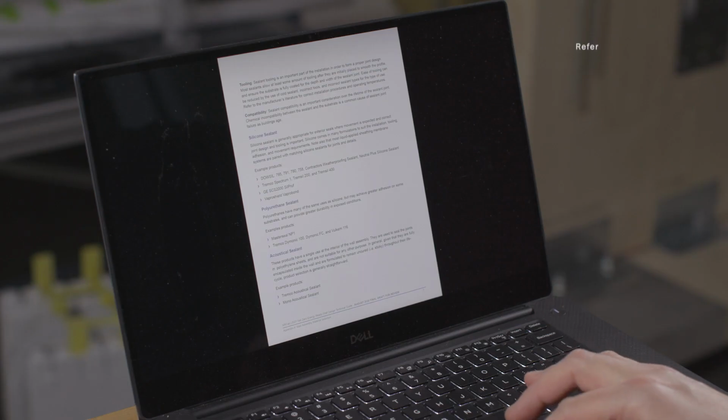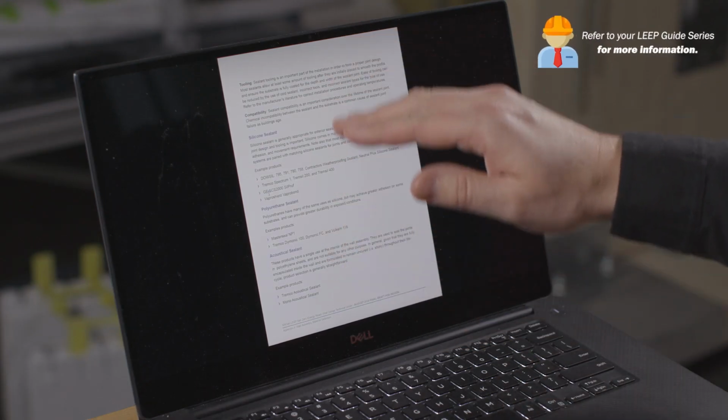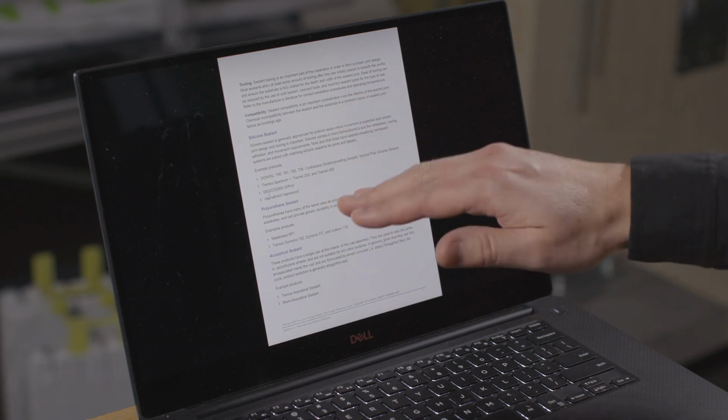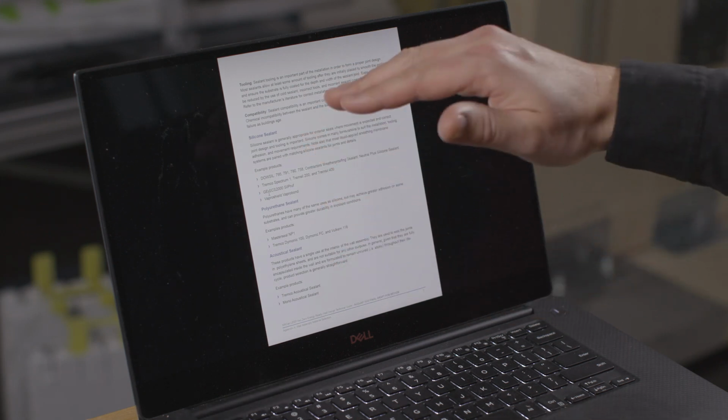With sealants, it's critical to properly apply them per the manufacturer's recommendations for surface prep, then tool the sealant. Proper application of the sealant, and the direction that you're applying the sealant, is also critical, and of course the compatibility. There are a number of different types of sealants. We've got silicone sealants, polyurethane sealants, and acoustical sealants, so some starting points here, and there's a whole number of different products. Silicone sealants tend to have the longest service life.